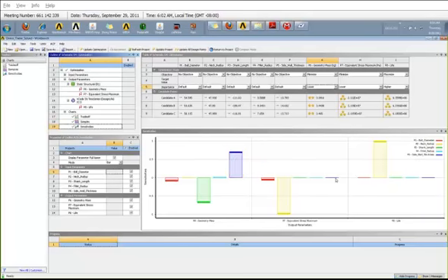That makes sense. Now let's take a look at the other output parameters for the sidewall thickness. It has almost negligible influence on my maximum stress, and also on my life. So if my objective is not to affect my fatigue life, but I want to reduce the weight of the part, I can vary this one to reduce the weight of my part without changing either my stresses or my life.